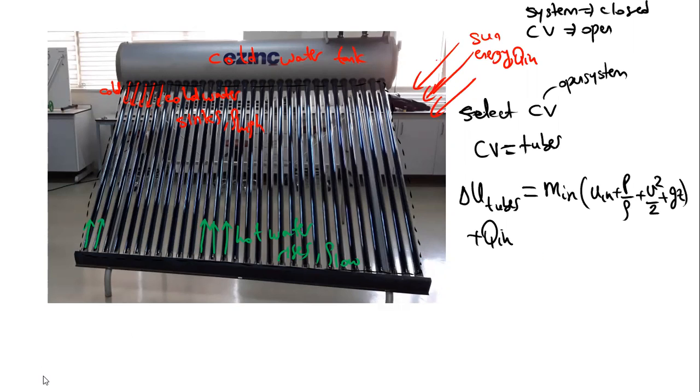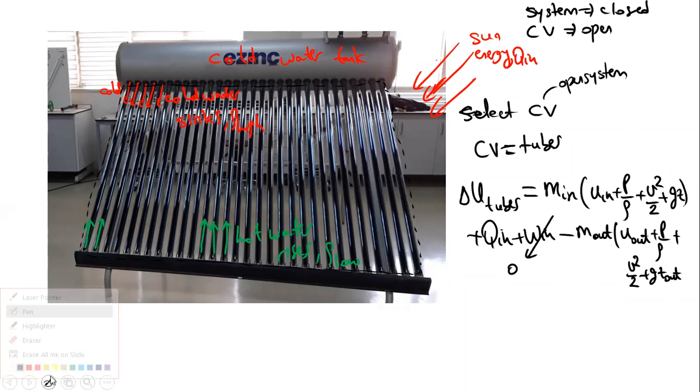Now let me add that term here so that you can see. Plus the work in term, that will be 0, because as I said, work in means something that rotates, for example a shaft, or electricity. The famous one is electricity. There is no electricity. And then comes the mass out. There will be mass out from the system. It will carry some internal energy, some pressure energy, and some potential energy and kinetic energy.